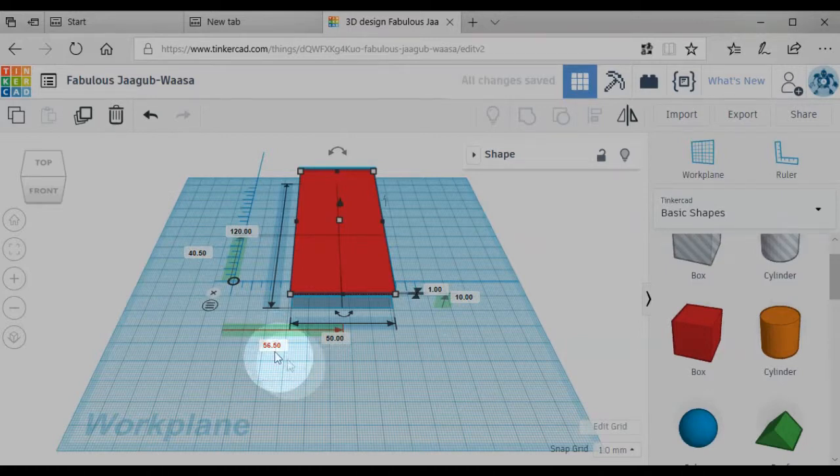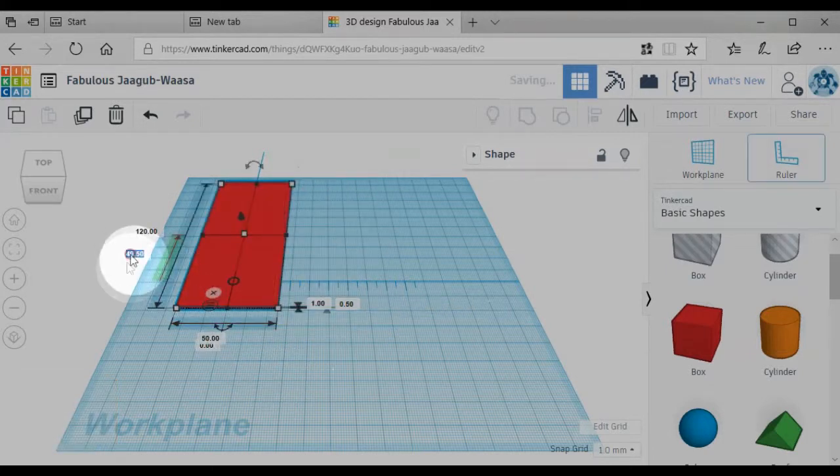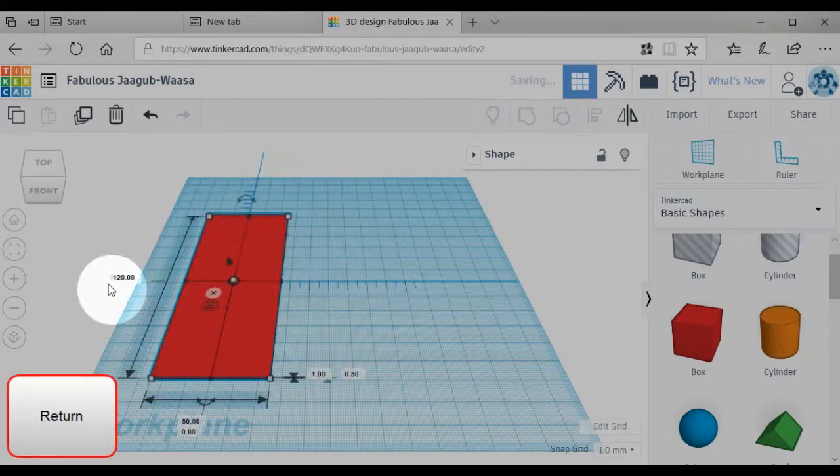Because we are orienting from the center of a box that is 1 millimeter tall, it must be positioned 1/2 millimeter high. This will help ensure the model sits evenly on the platform when it prints. To do this, select the number along the green z-axis arrow and type 0.5. Also, set the x-axis arrow to 0 and the y-axis arrow to 0. This centering will help later on.